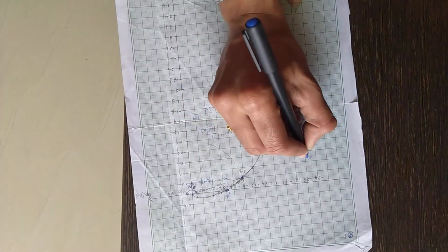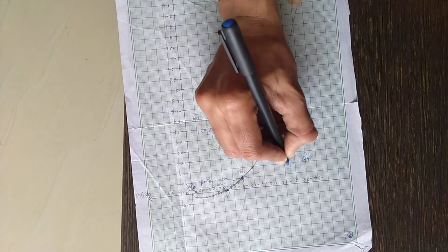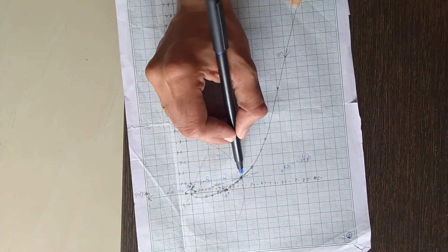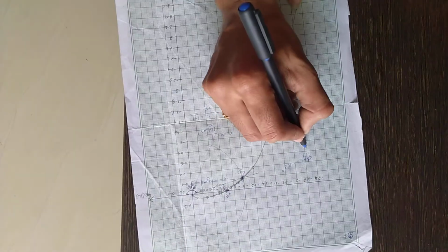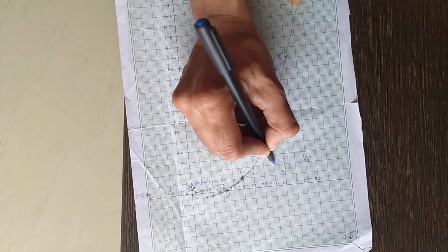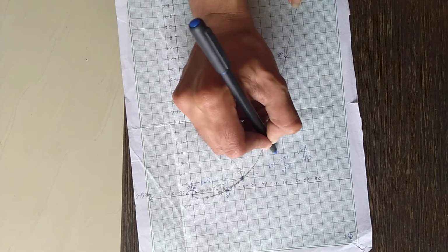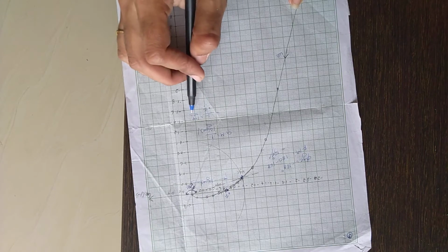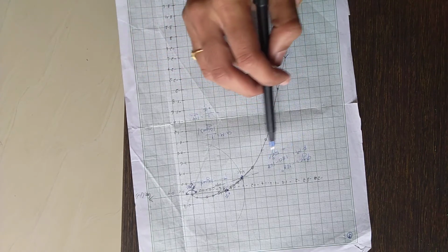So we got φgc equal to -168 degrees. Use a protractor to mark and measure, the value is -168 degrees. The phase margin is equal to 180 plus φgc. So 180 minus 168, that is equal to 12 degrees. Okay, so we got gain margin equal to 1.4 and phase margin equal to 12 degrees.